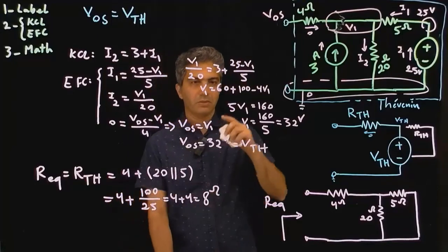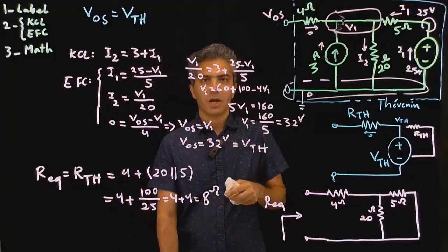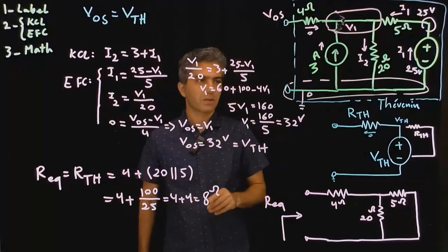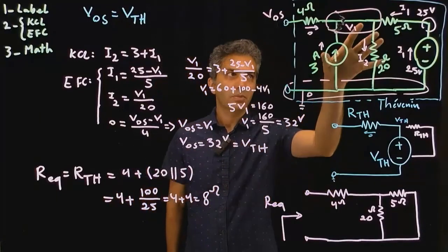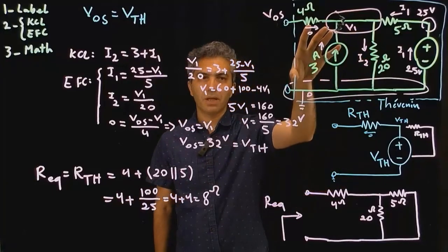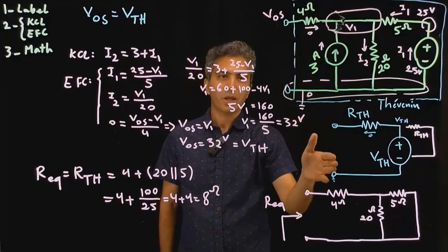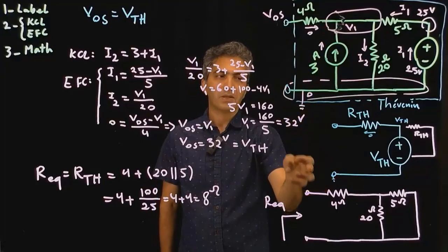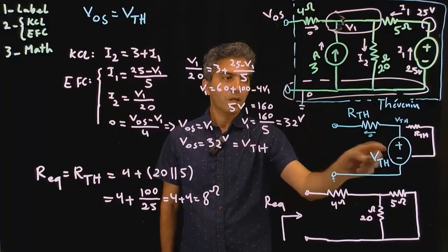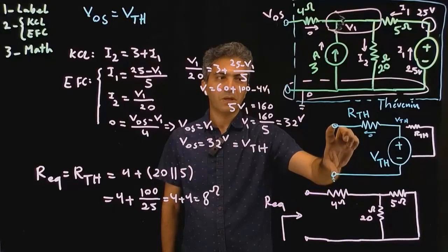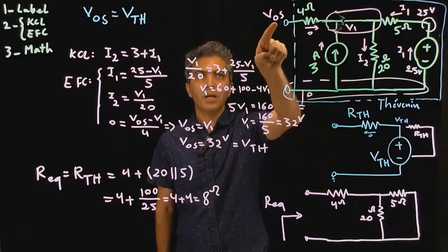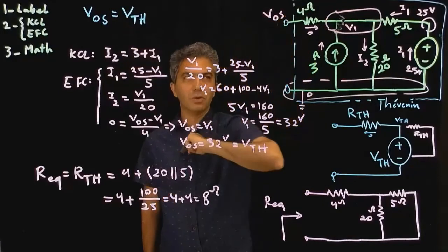I'm going to repeat the process one more time, then stop and move on to the next lecture, where we discuss the Norton equivalent. The claim is that I can represent this circuit with this model. Therefore, whatever happens to this circuit has to happen to that circuit. That includes the case where I leave this circuit open. If I leave this circuit open, the voltage across it would be V Thevenin. It's an easy calculation. So I do the same here, leave that open. The V open circuit is actually equal to V Thevenin.